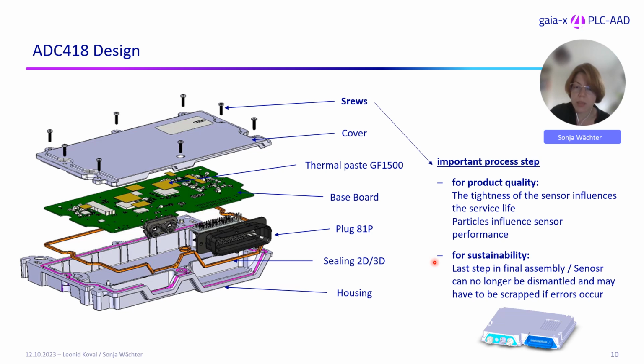And the process is also important for sustainability, because this is the last step in the final assembly. After we fix the screws, the sensor can no longer be dismantled, and therefore if we have an error in this screwing process, the whole fully produced sensor has to be scrapped.